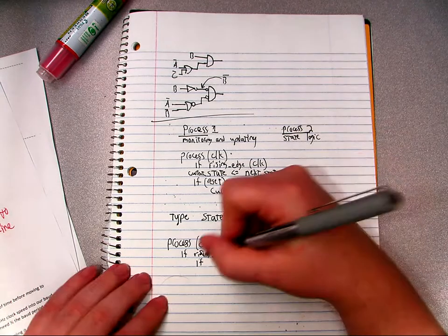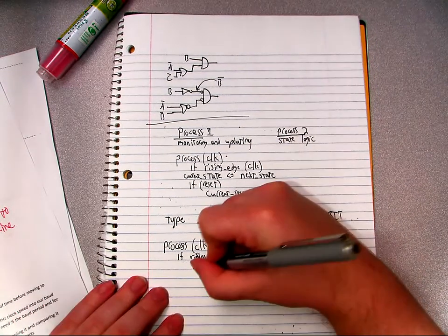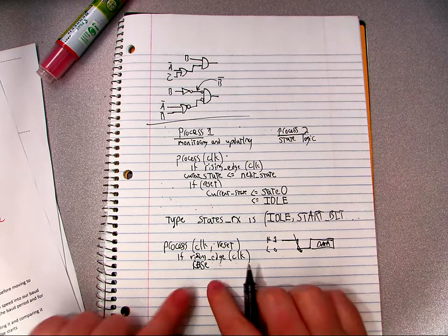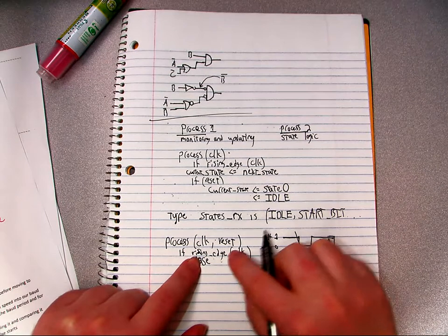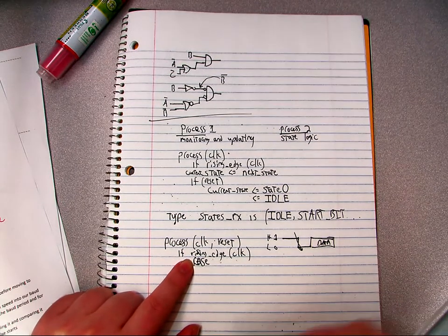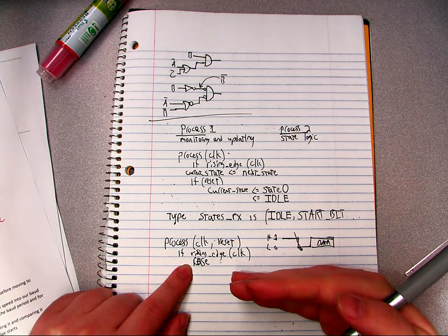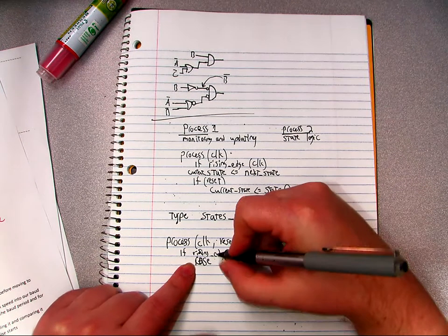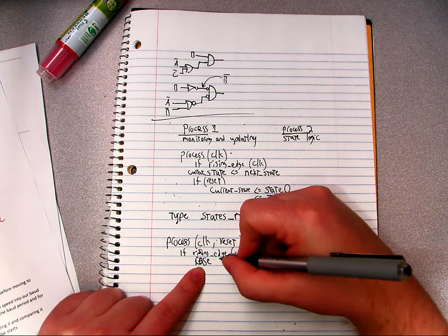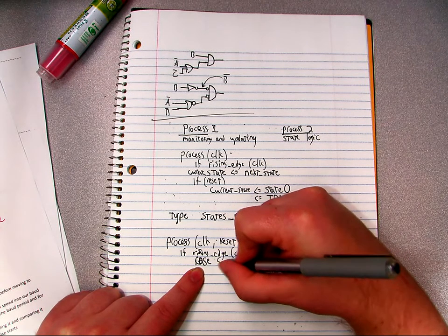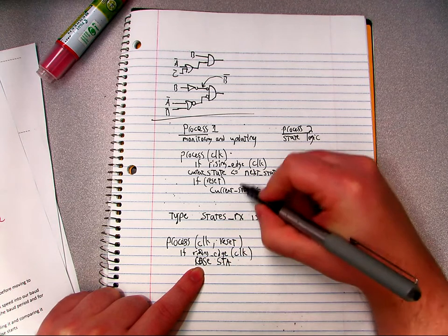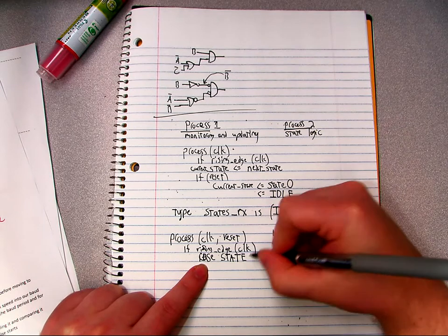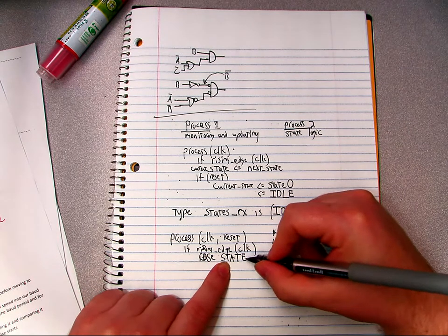So, let's start with the case machine. Almost forgot the case statement, which really is our state machine. And that case is going to go into this if statement, because you only want to execute the case on each rising edge of the clock. You don't want it to be continuous, and we'll see why later. So case on, and we're just going to call this state, because we don't need the next state variable that I was dealing with up here, so I can just use state. Case on this thing called state, which is a type of states Rx.